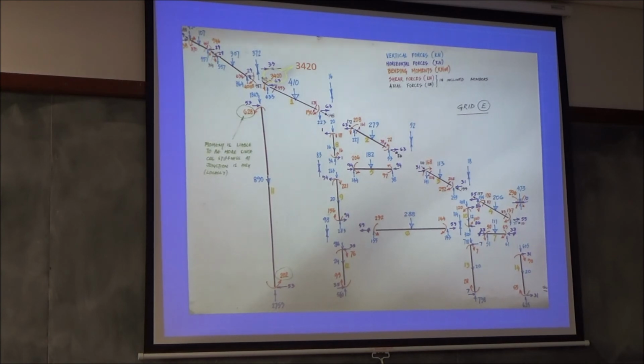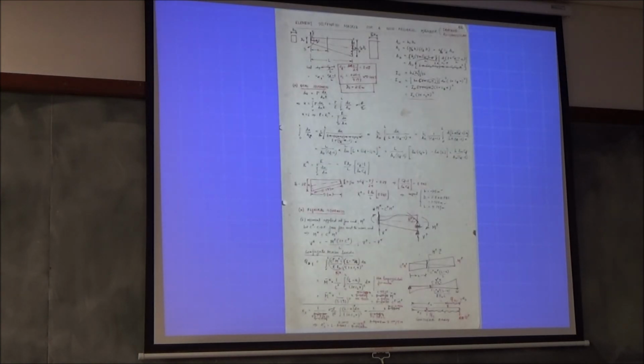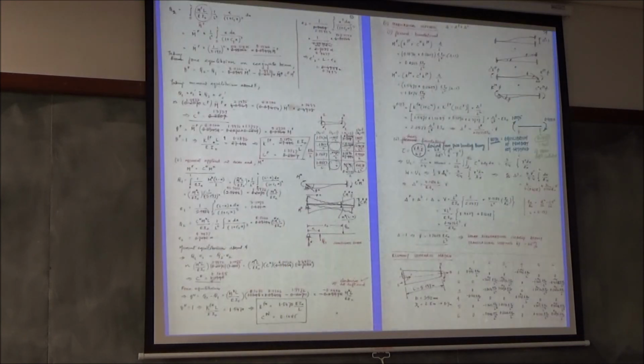I think I have a figure for that. Wait. To do all this, you've got tapered beams. So for your software, you have to find out the modified stiffness. It's not Fourier. You have to do from first principles how to find the tapered stiffness, how to find the carryover factors. A lot of fundamental work you have to do before you can write your program. So you see a lot of basics, structural analysis, and so finally you can validate it, improve it.